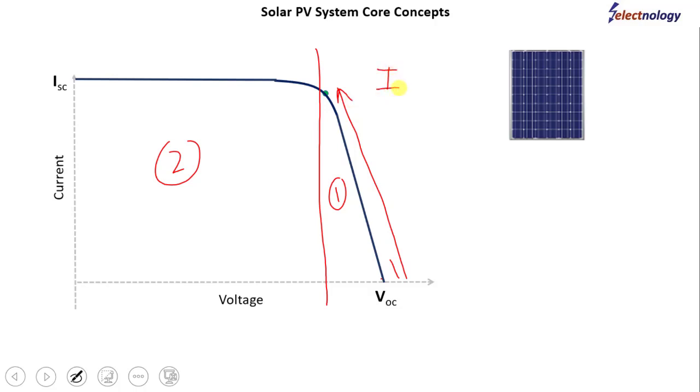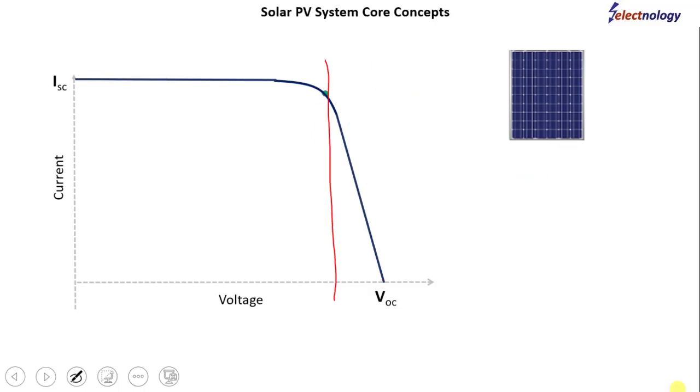So the relationship between current and voltage is reverse. This is what we have measured, and this is how the relationship between the voltage and current of the PV module works. In other words, if the load increases or the current increases, the voltage across the terminals will decrease. Now this relationship between the voltage and current of a PV module holds only up to a certain limit.